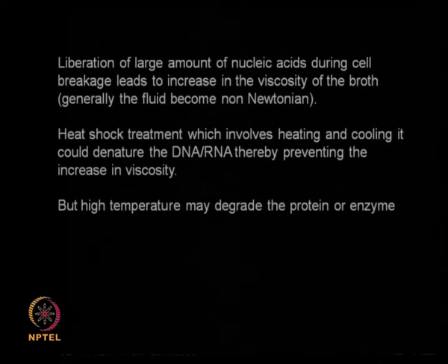So sometimes you may heat the material and then cool it, that is called the heat shock treatment, that will denature your DNA, RNA, thereby you can prevent the viscosity. It sounds easy, but then when you are heating it you may be denaturing your product also. If your product is enzyme or protein, the product itself may get denatured, so you need to be very careful about it. So you have to understand that the viscosity of the broth after cell breakage is going to rise considerably, and it is always a non-Newtonian type of behavior.